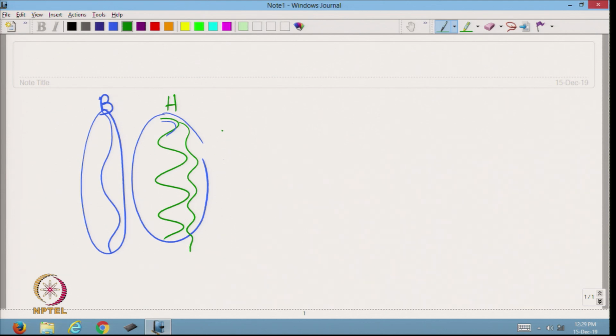The bandage dimension will be stretched; more stretch will be there in bandage H than bandage B due to higher crimp. So, stress relaxation will be high in the case of bandage H, that is why the pressure drop will be high.